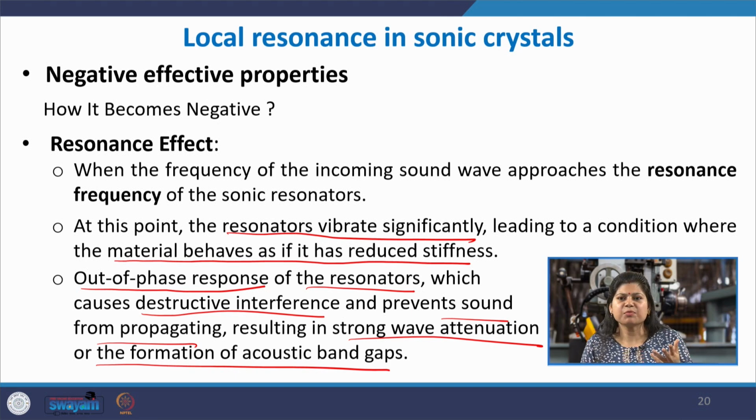That concept has been utilized in the Helmholtz resonator, in the perforated and microperforated panels, and also in the acoustic panels, the general panel absorbers. All of these are resonance based absorbers. The incident sound wave is able to drive the structure into resonance or very high vibrations, and because of it there is loss in the sound wave energy.